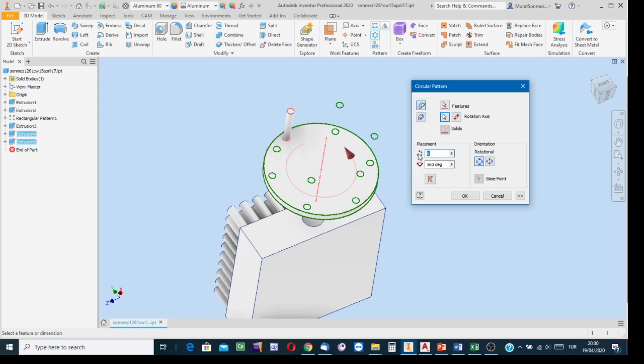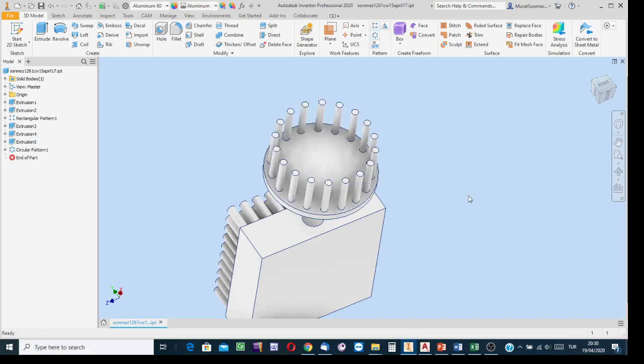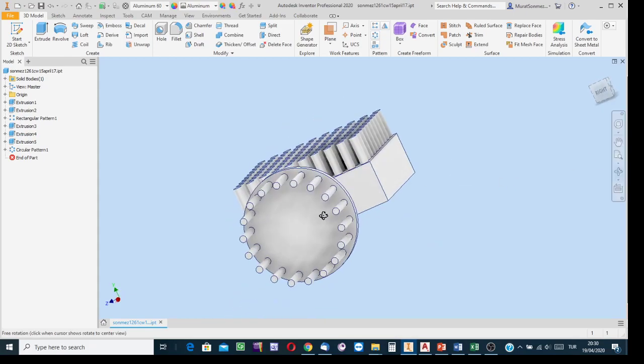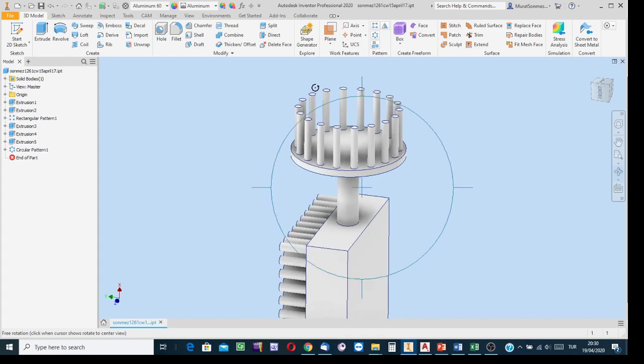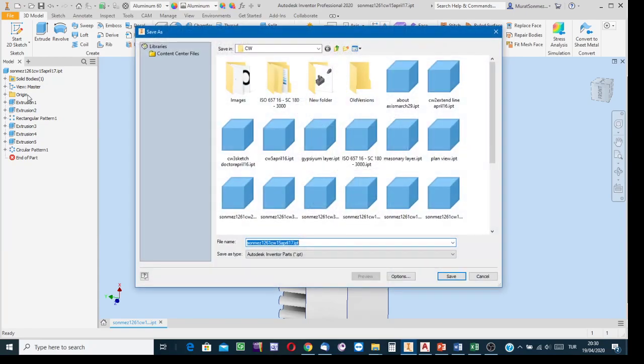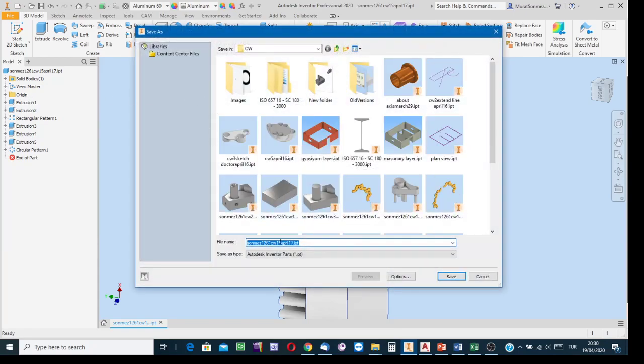Say that in our example, not 6, but 18. Enter the distribution angle into this box, right? Full. And then the rest, click on OK. That is it. Yes, you see, no difficulty. Since the axis is defined for a revolved feature, to say that about the axis of this disk, just at this stage I indicated the edge of the disk, and the rest is achieved by the software. Clear, I think. Okay, save the file, save as classwork 16 for today.